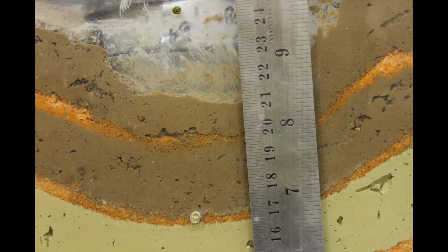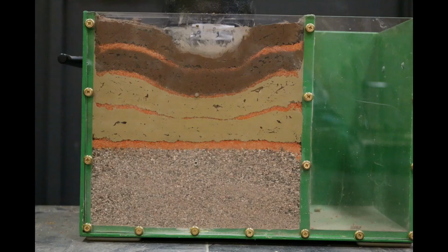There are two main reasons that can cause this situation to occur, which are the response of each soil based on its own particular properties, and that the major impact of force is dissipated by the first layer. Note the boundary where clay and sand meet. Both layers experience the same amount of force, but the clay is more distorted. This is because the clay is more compressible than the sand above it.